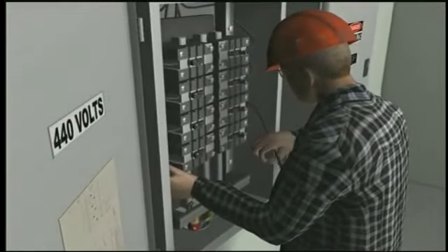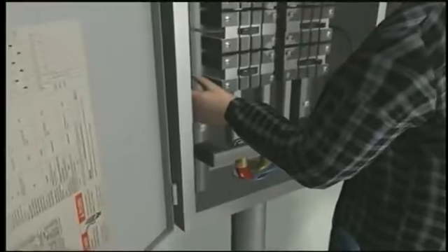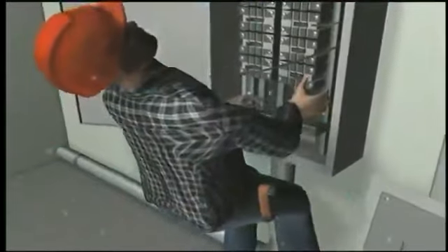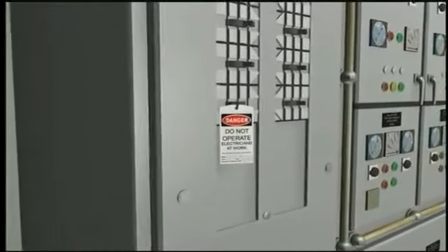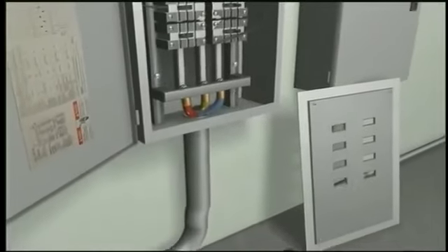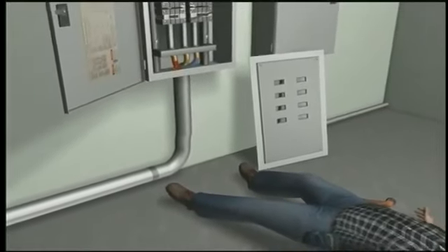As the electrician was fitting the new cable into the panel, his left hand came into contact with the panel's main bus bars. 440 volts of current passed from the bus bars through his left hand, across his chest, and out his right hand that braced him against the panel, electrocuting him. At some point, the tagged-out isolation breaker had been cross-wired with another breaker. The electrician did not know that the panel he was working on was never de-energized.